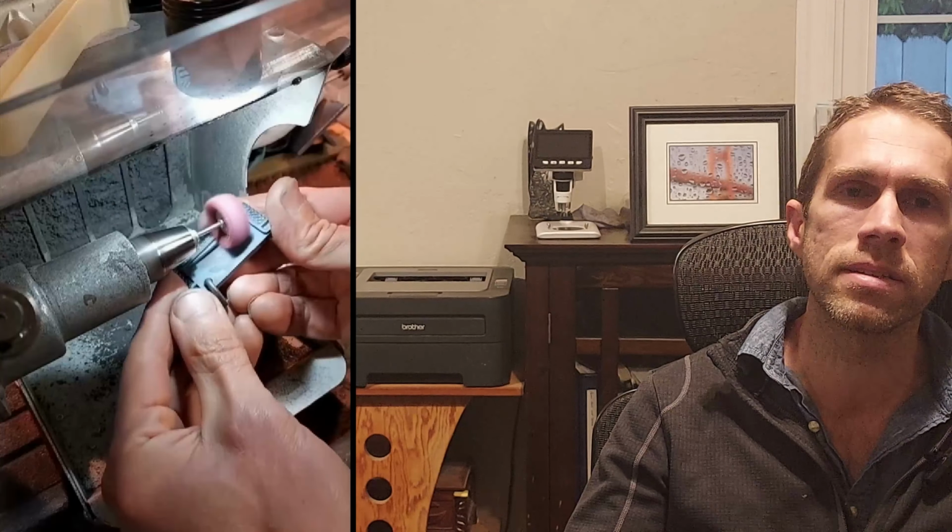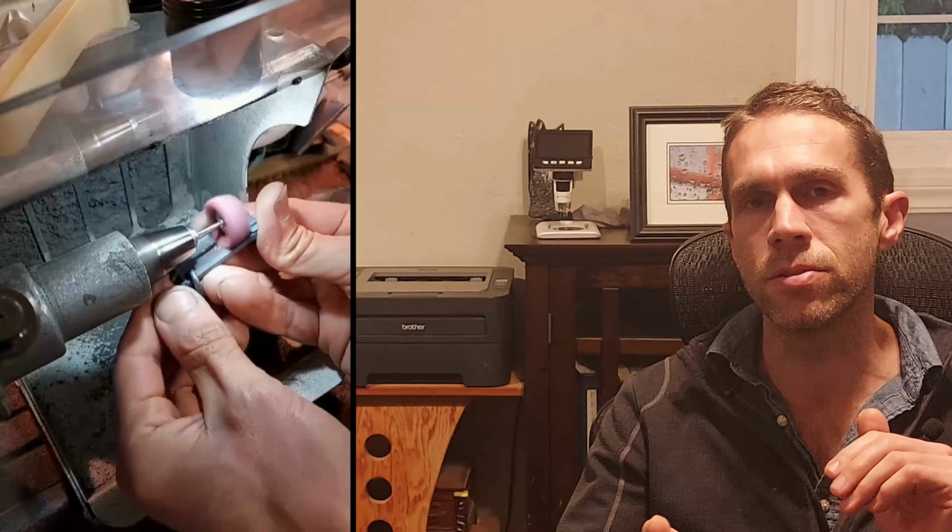You might be using some components that were cast and then soldering them onto a ring shank that you forged, and then filing it and hammering it into the shape you want. You might add a few other little pieces here and there until finally you have your finished piece. But regardless, you're typically taking multiple pieces, combining them together using soldering or cold connections, that's also a possibility, and that's your finished piece.